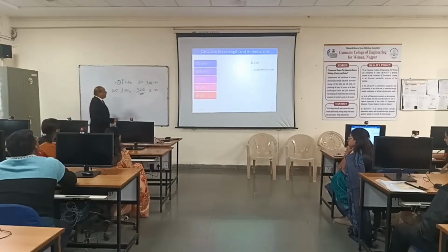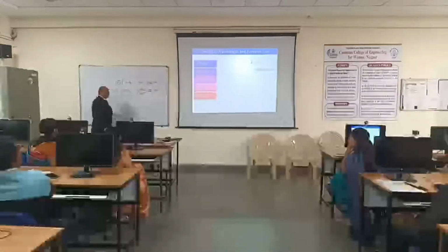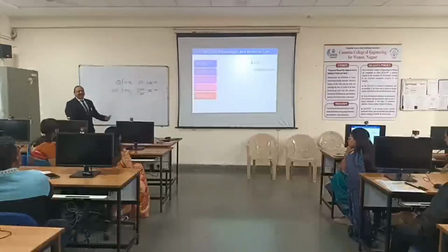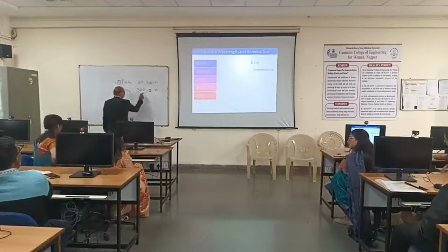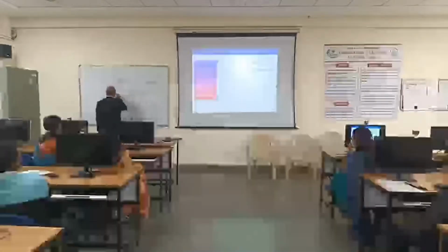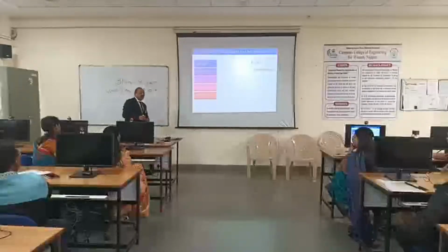Corresponding wavelength. Okay? If someone says, let us take 10 meter is the wavelength, how much is the corresponding frequency? It is in meter, and this answer is in megahertz. So 300 by 10, one zero will get cancelled, nothing but 30. 30 megahertz is the frequency. That is the way you calculate.